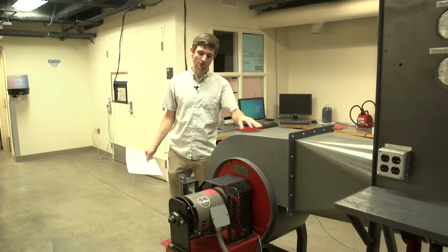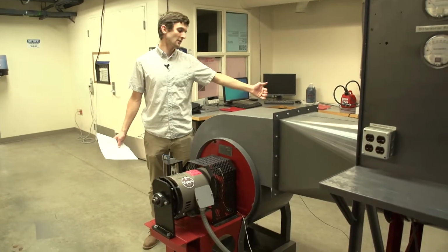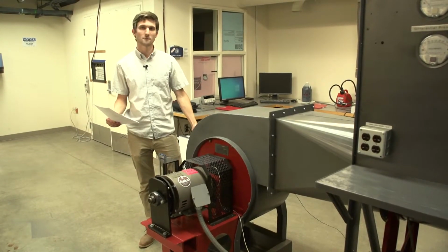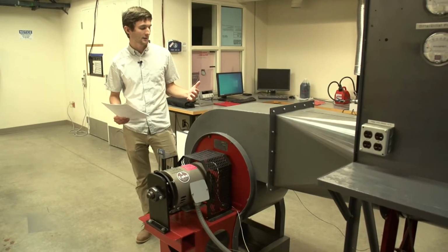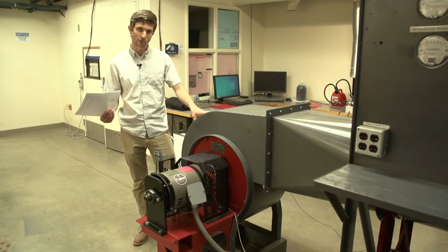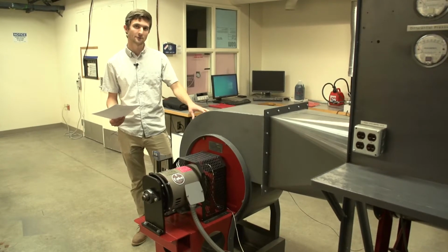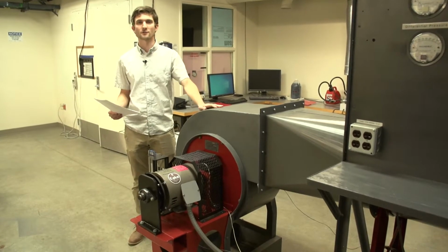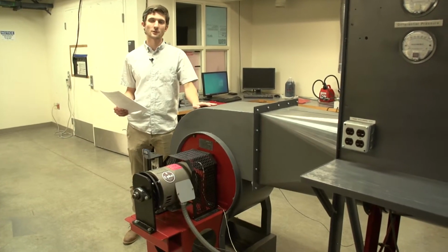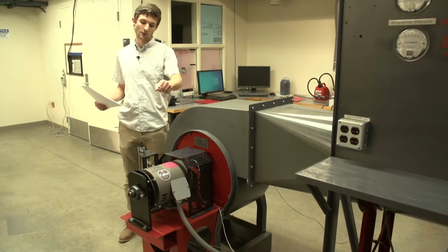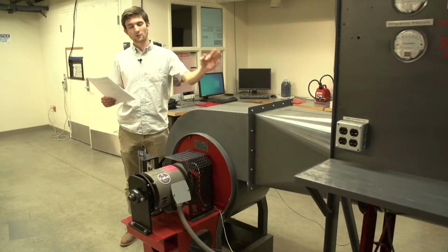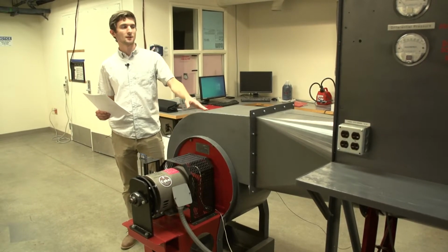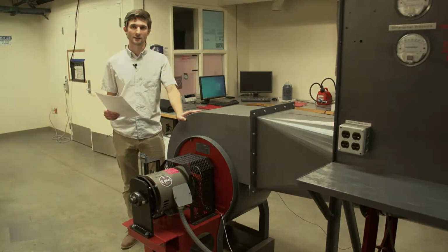we have the fan driven by this motor where air enters at the other side here, and it's called a centrifugal fan because air is thrown to the outside of this enclosure via centrifugal force imparted by the impeller blades. Then the air travels down the wind tunnel to the flow restrictor at the other end. The system consists primarily of the fan, the motor that drives the fan, the wind tunnel, and the flow restrictor, as well as the instrumentation, which I'll talk about next.